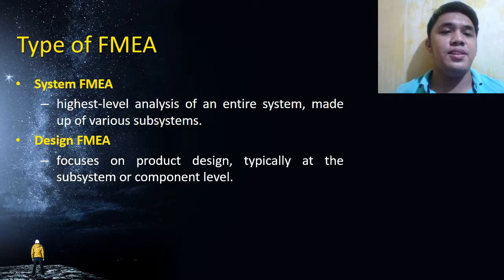Design FMEA. The focus is on the product design, typically at the subsystem or component level. The focus is on design-related deficiencies, with emphasis on improving the design and ensuring product operation is safe and reliable during the useful life of the equipment.